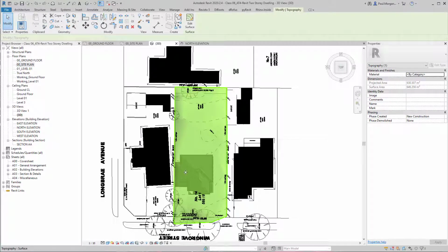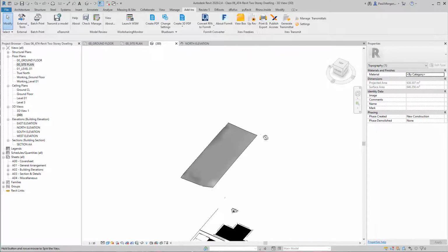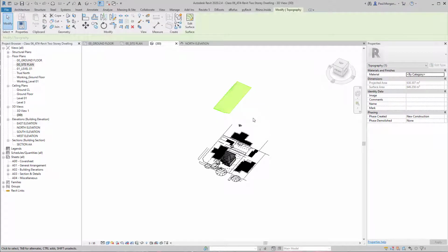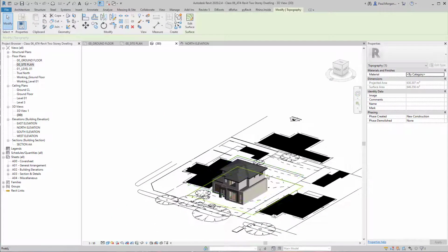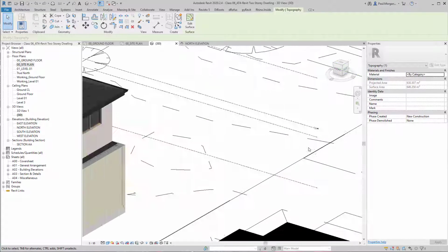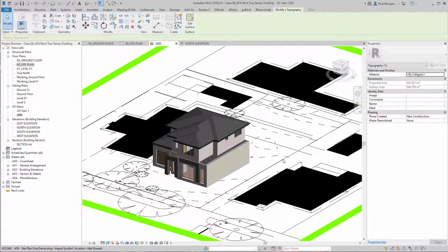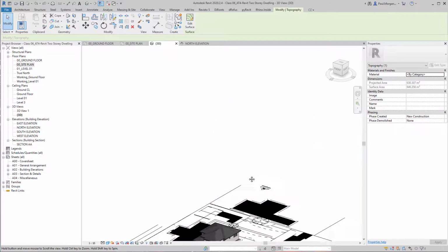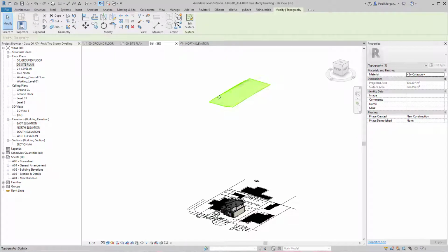The next thing I need to do is move the model. You'll notice that because the heights were taken, the site that we're using is of a much higher site than the heights that we did at the start of the project. We need to move those levels in the project. So at the moment we're sitting at like 54 meters above sea level or something like that, but up here we're at like 130 something.